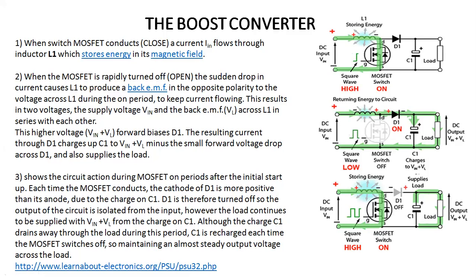So here, when we make the switch off, that produces the back EMF, and it works in the opposite direction with respect to the input voltage. This higher voltage is nothing but the voltage across the inductor, which we call back EMF. You can say E or E suffix B, meaning back EMF, or we can say VL, which has the same meaning. We say back EMF as the voltage across the inductor.